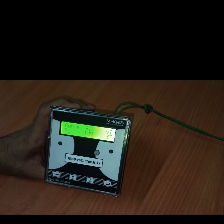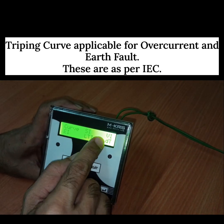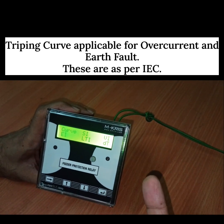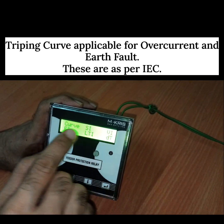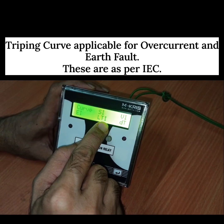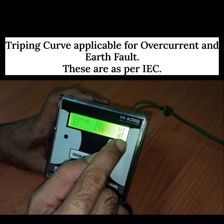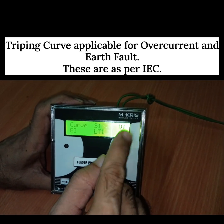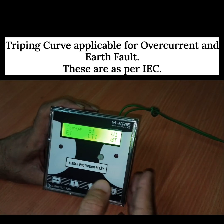And lastly, but very importantly, this is the tripping curve, which is applicable for overcurrent and earth fault settings. These are as per IEC: standard inverse, very inverse, extremely inverse, and long time inverse curves, and the definite time characteristic. When we choose the definite time characteristic, then the setting of over voltage time delay will be applicable.